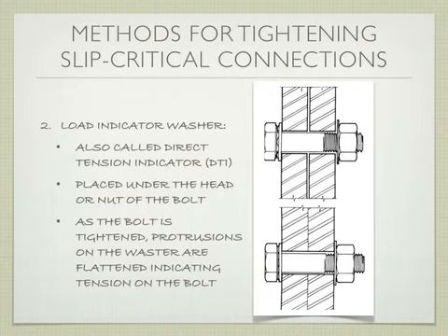I have another one right here. This one has it on it too, so you guys can look on this bolt. There are the little tension indicator washers. Once those are flattened off, you know that this has the desired tension.